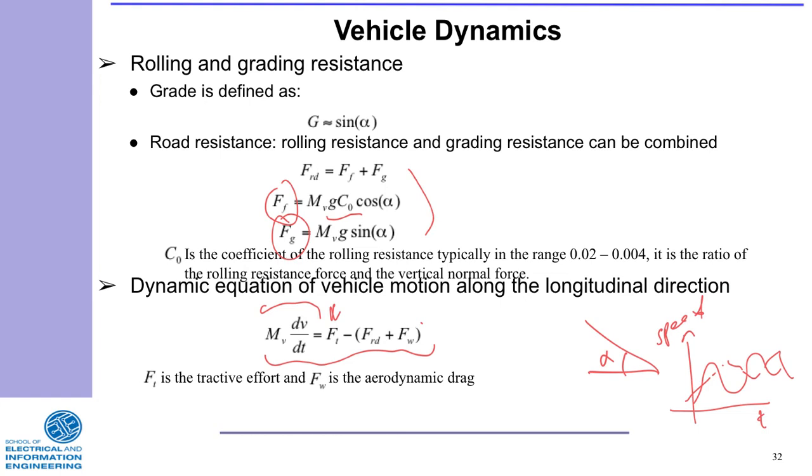Based on that drive cycle, which could be a route from here, let's say, to Pretoria, it will really show how the vehicle drove and the gradient along the road. And based on that, one could extract the maximum gradient. And you know the mass of the vehicle and the aerodynamics of the vehicle.